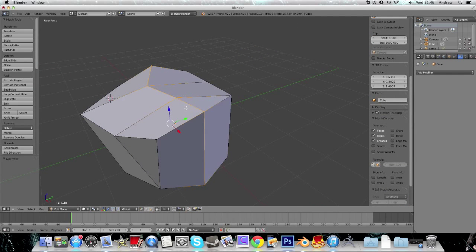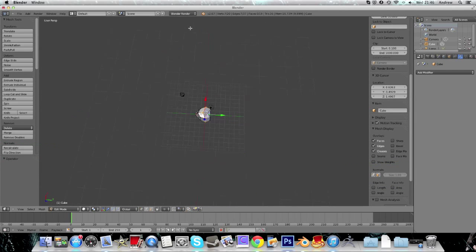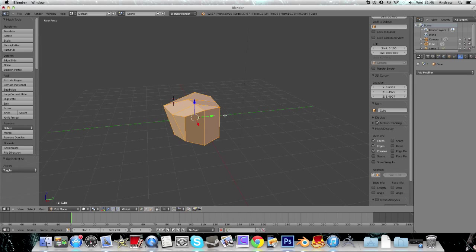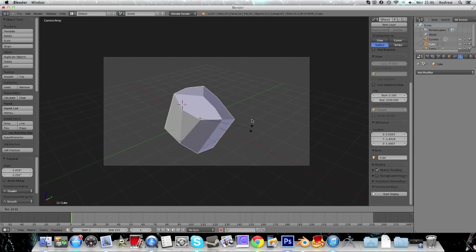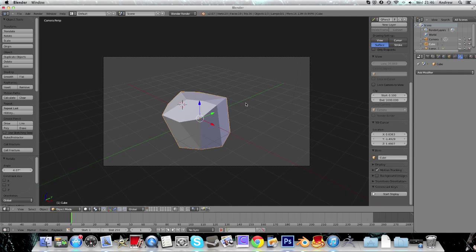Another one is with ring loops, so we can see that we've got an entire ring loop all the way around the shape here. A handy way to see around the shape is if I select the whole thing and press R twice, that's rotate twice, and now I can get this cool 360 look around my shape, and I can just right click to put it back to its original position. Maybe we can go into the camera view, and maybe we don't want to view it quite from this angle. It's easier to press R twice and then put it to the right position than it is to move it like this, depending on what kind of effect you want. So that's cool. And I'm just going to tab back into edit mode.